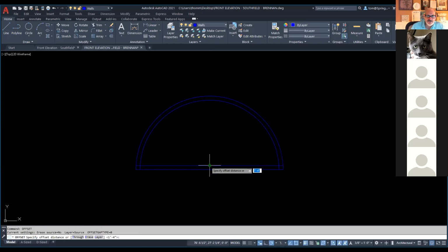And then from there, I'm going to draw a line from here up to here. Okay, why is that not showing up there? Offset gap. Oh, I don't want that. Okay, I want the line command. So let's just go here, here to here. All right. And then I want to offset a 1/2 inch in either direction. So we can go here